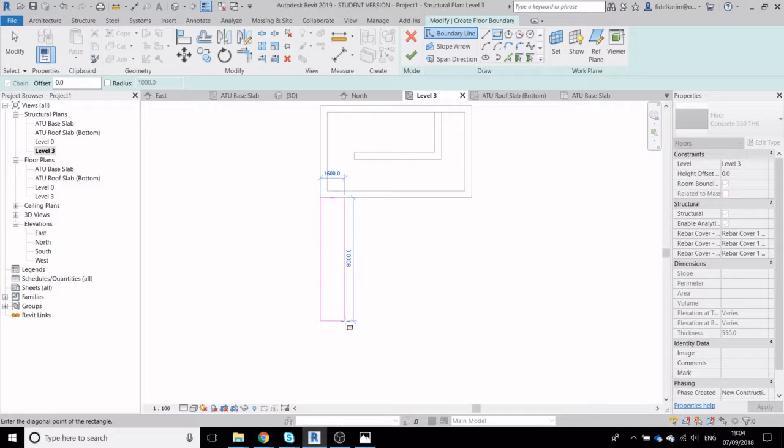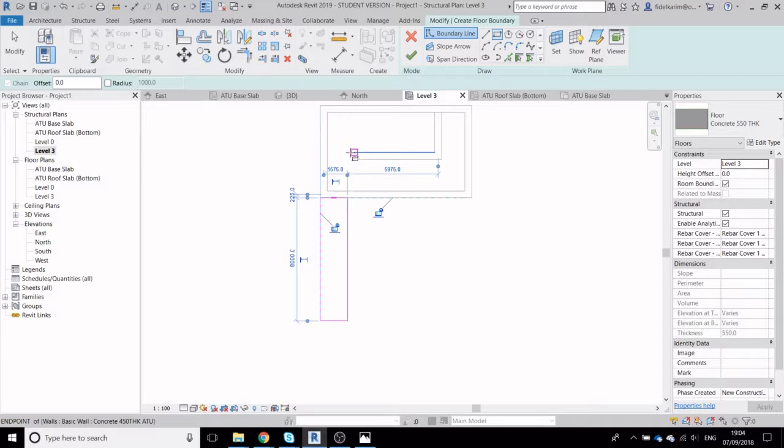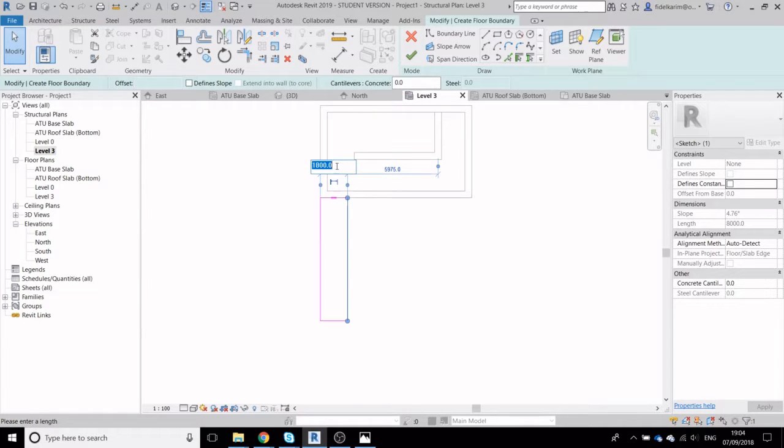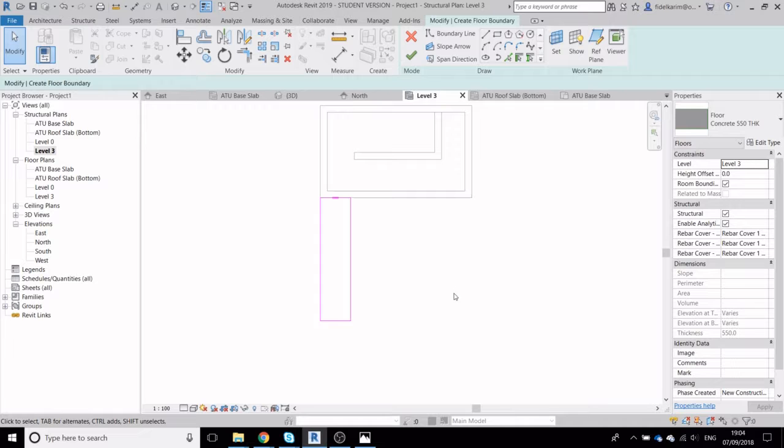I'm just going to use Revit's automatic thing, and I want it to be 2 meters wide, so I'm going to put it here because it's snapping to that. So if I select this, I can now hit that, say, oh, nope, don't want it 200, I want it 2000 millimeters. There we go.